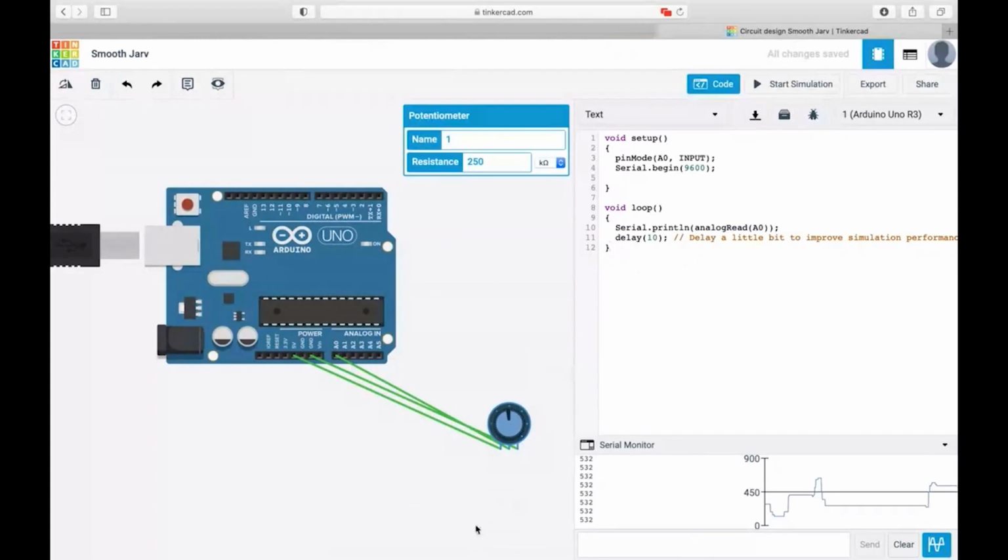This is a potentiometer, which is an analog sensor, where the displacement of the wiper is converted to a voltage form. Sensors are basically transducers which convert one form of energy to another form of energy. They sense physical phenomena. If it is a temperature sensor, that temperature is recorded and reflected in terms of an electrical quantity, that is, a voltage.